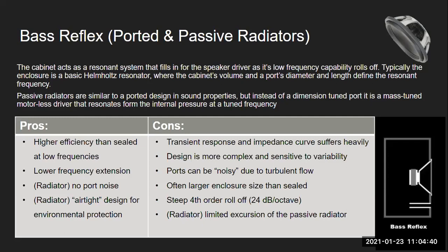However, the issue is that, since you're trying to excite this resonant system, the transient response and the overall impedance curve get worked pretty heavily. So the transient response tends to suck. I don't know if there's a better explanation, but the way I like visualizing this is that typically your transient response suffers the more you try to get it to play out of the band of the speaker.